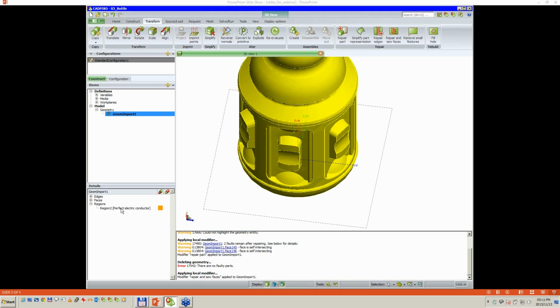If you read there in the Help Center or if you contact support, we will tell you to apply the combined field integral equation, or the CFIE, to your model, which will improve convergence. And you can only do that when you have a valid solid. So in this case, we will be able to use the MLFMM with that improved method for convergence.